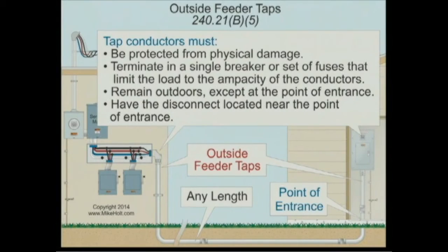Now, outside taps. You have to understand what we're trying to achieve here. We're really worried about wiring that's inside of a building. When you're outside a building, what can happen? You're not going to cause a fire. So when you're outside the building, the rules are a little bit different than when you're inside the building. It says this: outside the building, you can run that wire as far as you want to run it outside. We don't care. All we care about is that when you finally end, like any tap rule, you have to do what? No less than a calculated load.